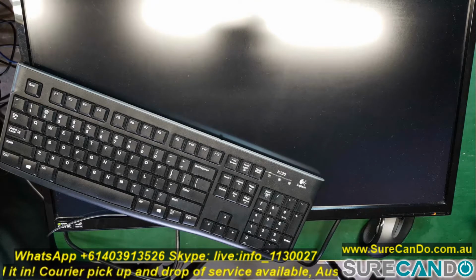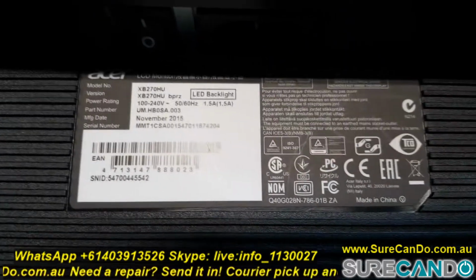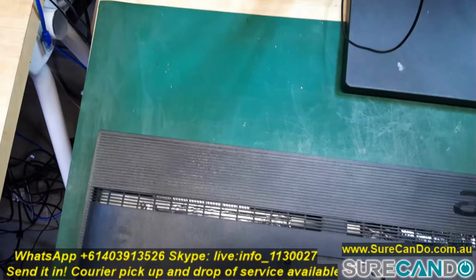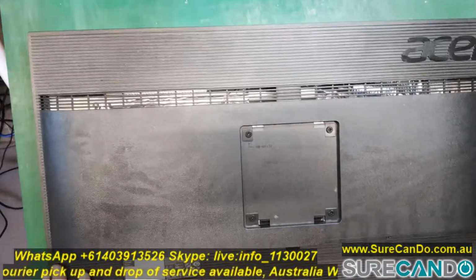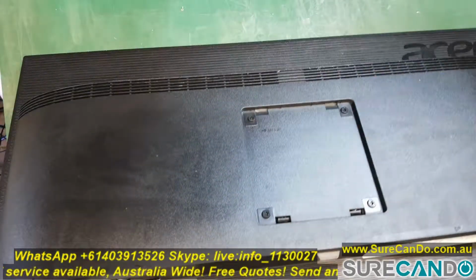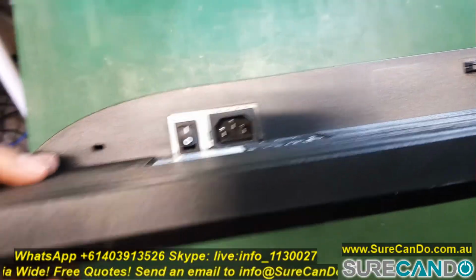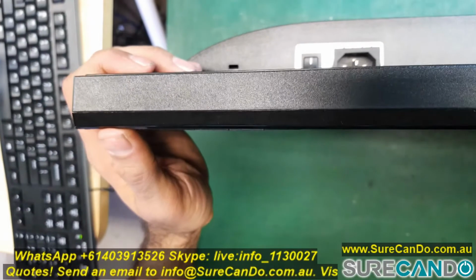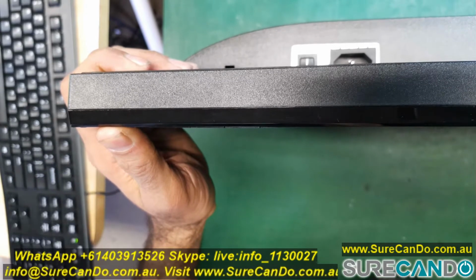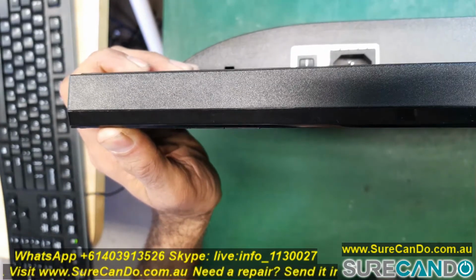Let's disassemble the unit. So here it is. This is the Acer Predator XB270HU. It's a 27-inch gaming monitor. Let's give it a go. So the only 4 screws I can see are these ones here, and I found another one on the display port. So remove 5 screws altogether, and you need to use the prying tool and gently pry the monitor from all around the edges, and the back panel actually comes off.